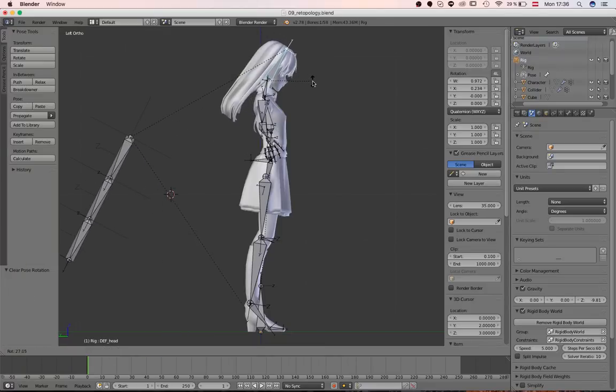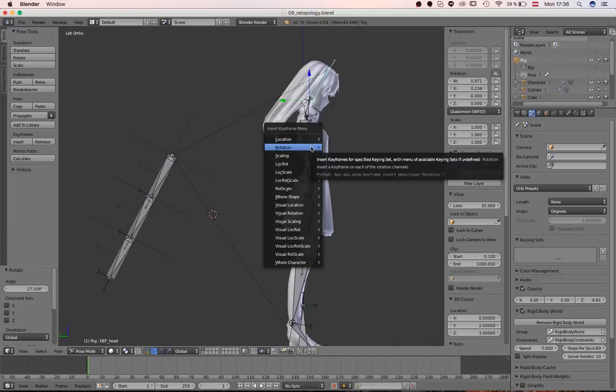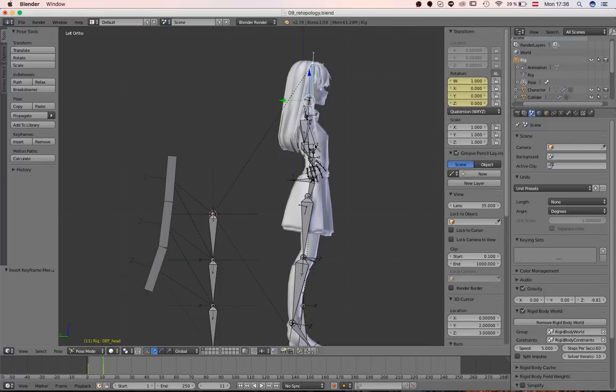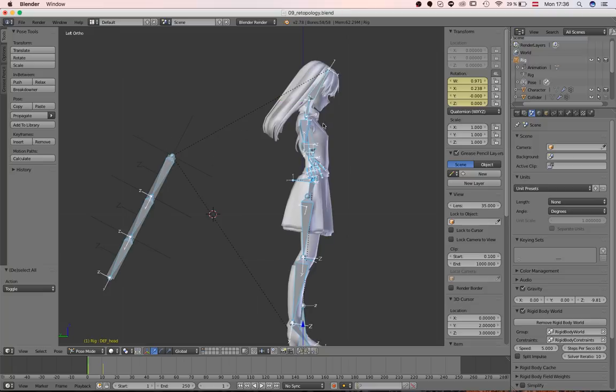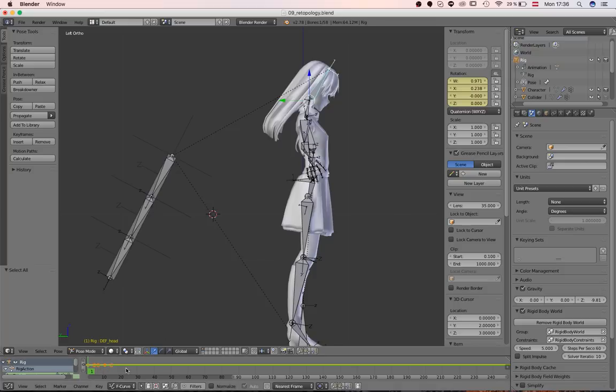While it does move when you rotate the hair, for example, it does not work when you add a keyframe. Add a keyframe here and a bit later another one, and see what happens. The chain just stays at this position. This was something that I overlooked in the last part, so I quickly want to show you how you fix that. Let's remove the keyframes again